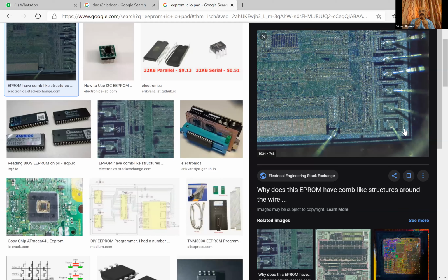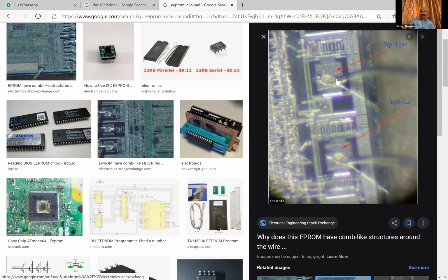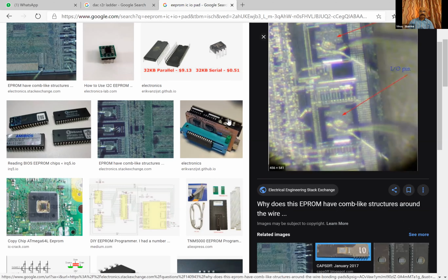So these are square metal pads, okay, through which a silicon chip output or input is connected to the IC's body chip pin, okay. So using a thin gold wire or some anodized aluminum specialized wires, okay, and this is how it looked. You know, this is an IO pin or input pin, anything it can be, and thin wires are shorted from here and connected to the output. Is this understood? First of all, let me see. Any questions?